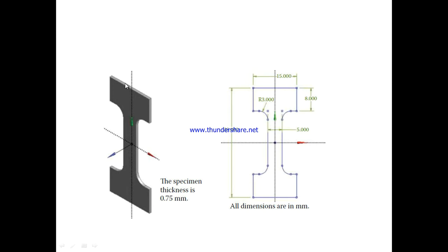After making that extrude, at the bottom corner we are going to make a fixed support. In the top corner we are going to apply the load, which is a 50 megapascal load. Once we apply the load, in between, a little bit of crack will take place. Before the crack, how much buckling will take place, that is what we are going to calculate. After applying the load, whether it will crack, buckle or fail, that we are going to analyze using ANSYS Workbench software.